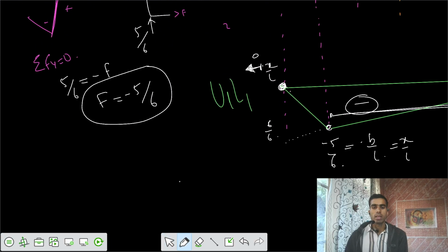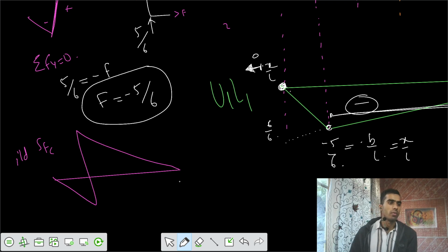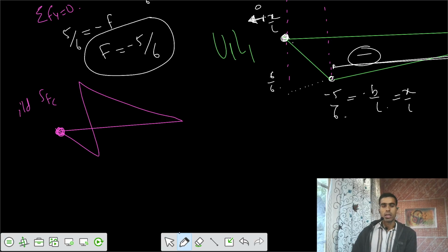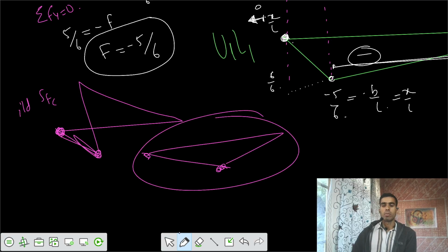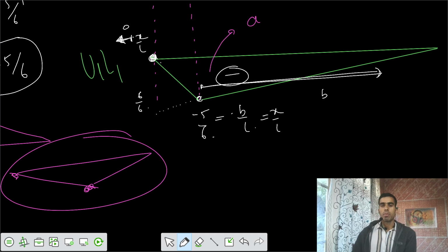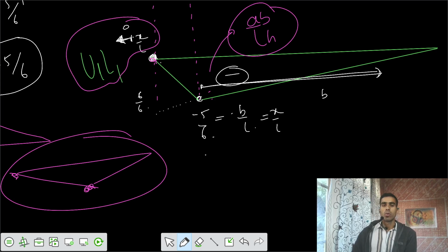It is some sort of ILD for shear force at any section C. We have this ordinate. Based on that, at the critical location of 1 we had 0 ordinate. That means only one peak has developed, so finally we can say there is a triangular variation. But it's not that of ab by lH. It has developed because of the condition that force is 0 when the load was at joint A. Otherwise, there would have been some value here also.